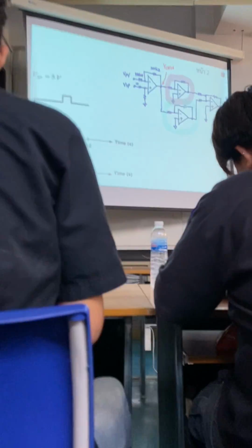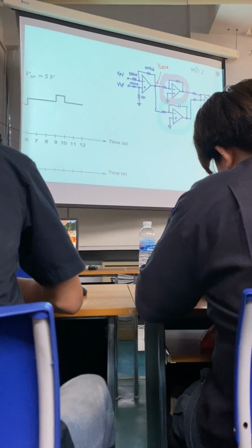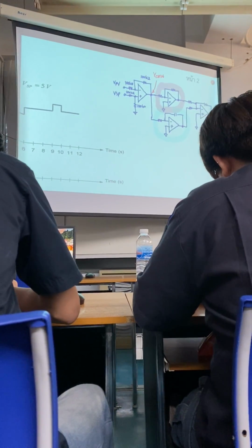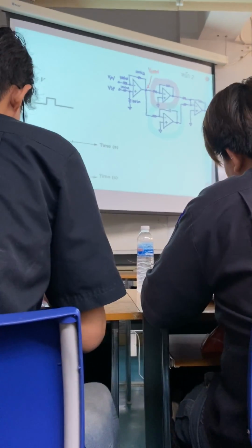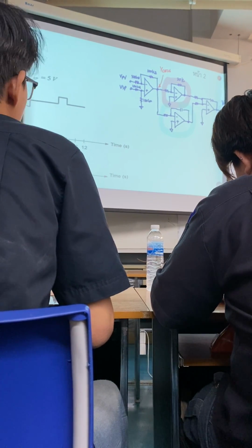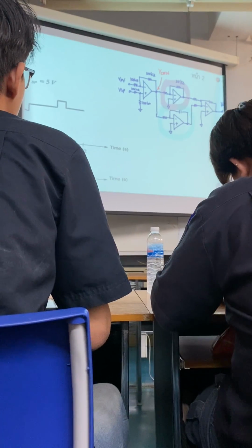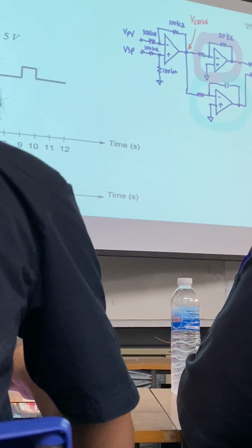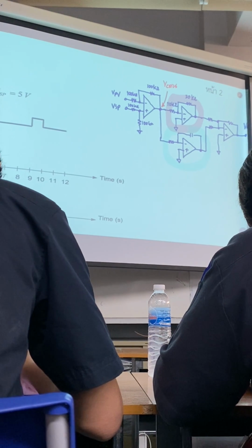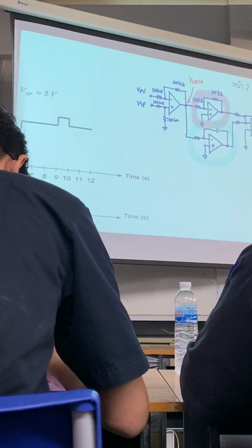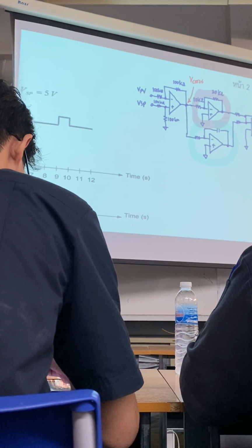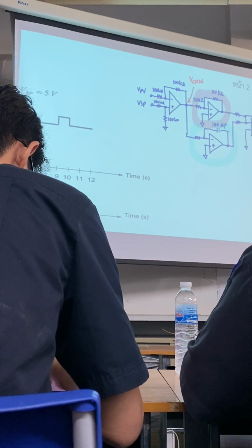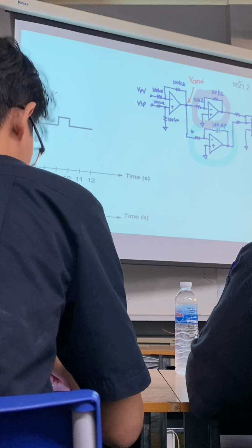100k ohm, 100k ohm, 100k ohm. In the P controller, I set the gain equal to 3, and I assume the feedback resistor is 30k ohm and RI is 10k ohm. In the integrator, I will use a capacitor with a value of 100 microfarads and 10 kilo ohm.